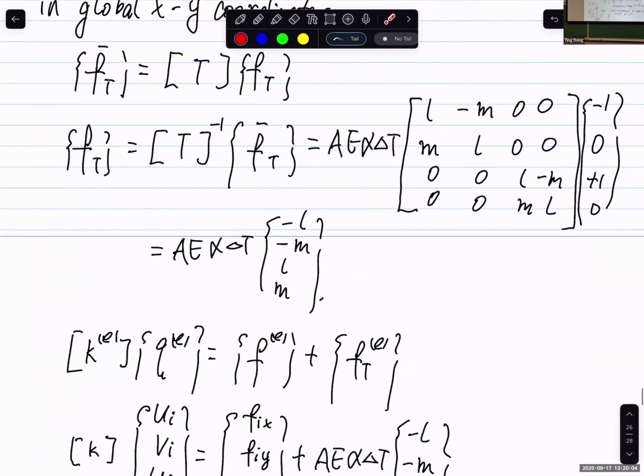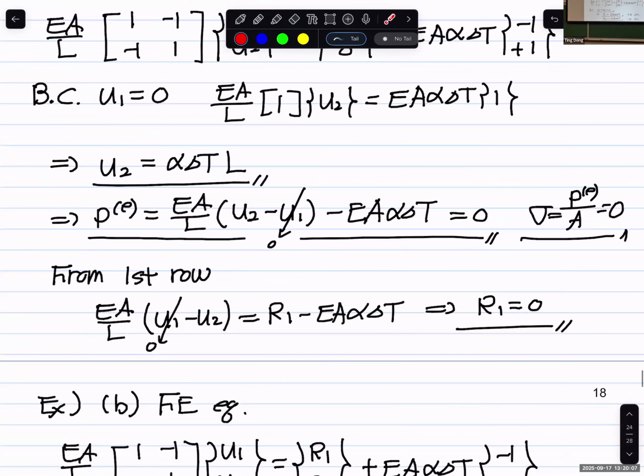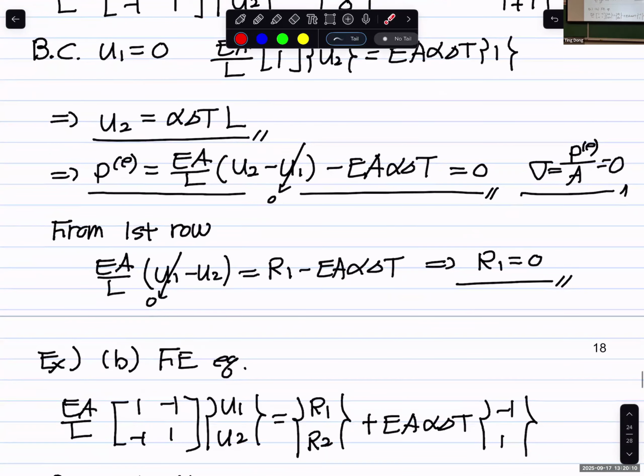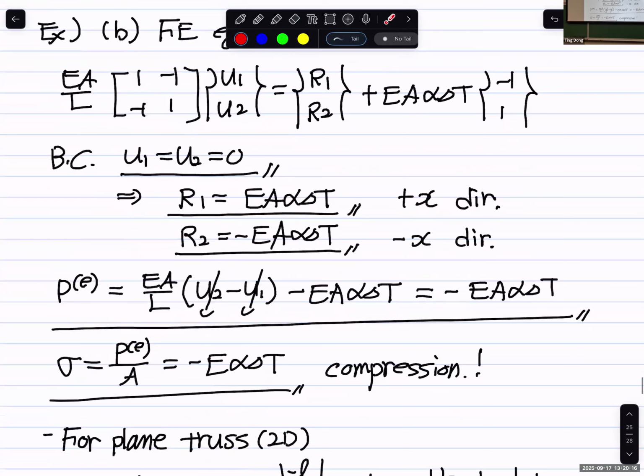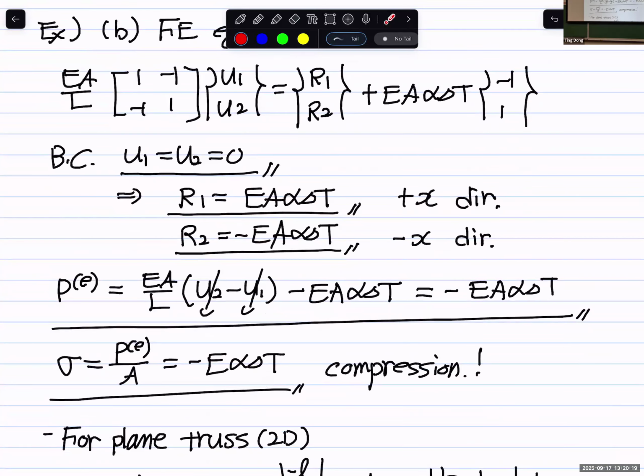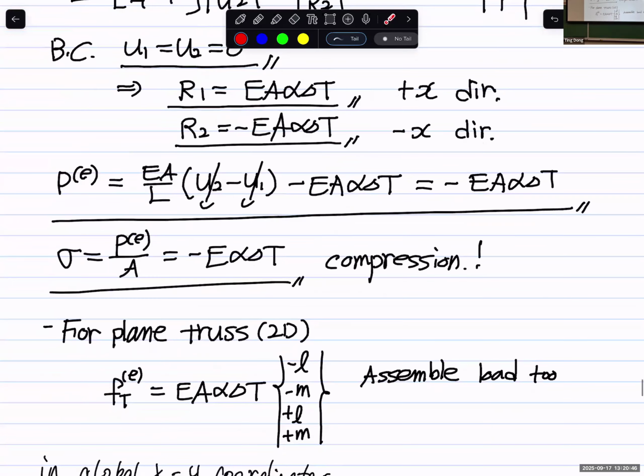Let me check the example Kim did in the last class. So, oh, he did the calculation of the stress. For calculating stress in tension compression, this is the equation, right? We already calculated the element force for all 3 elements. If we want to know the stress in the structure, divide by cross-section area, because this is a simple tension compression situation. It's sigma equal to P, the element force or internal force from mechanics of materials, divided by cross-section area, and it's constant at every point in your bar. So you can do that after class.